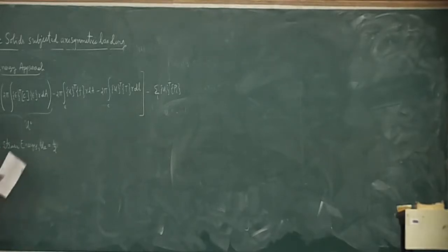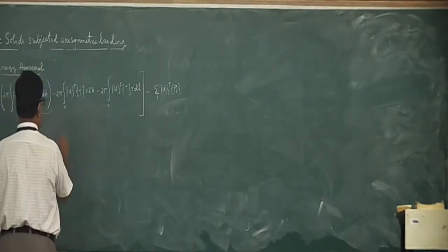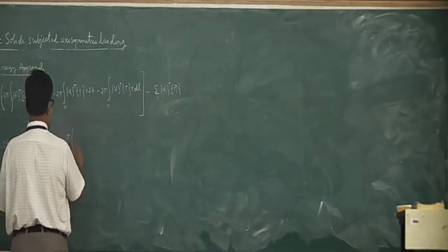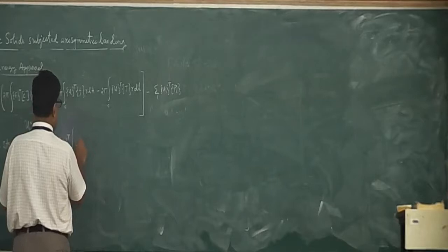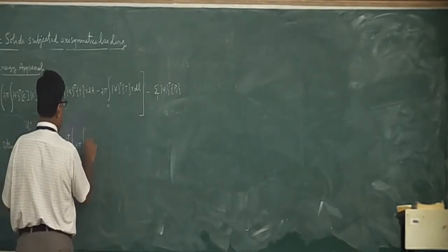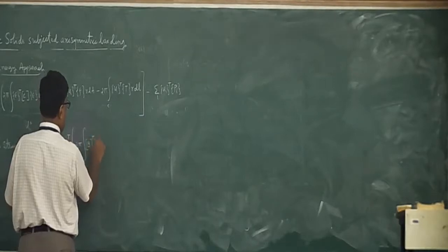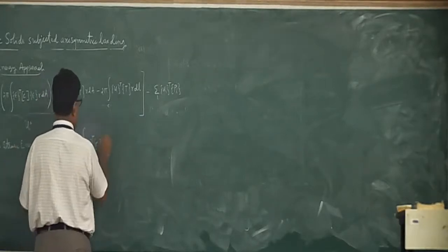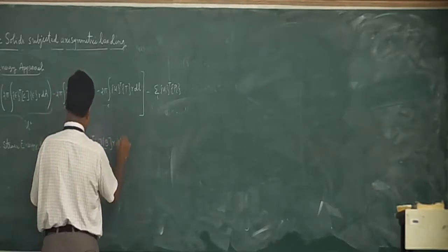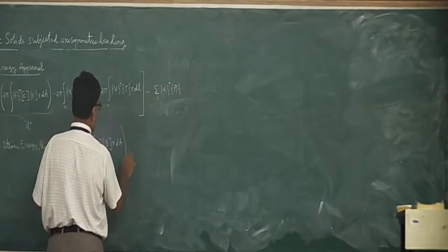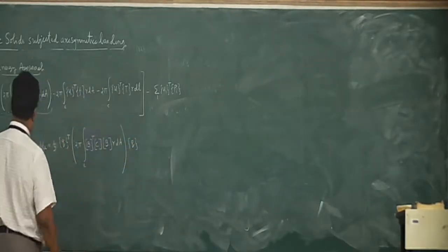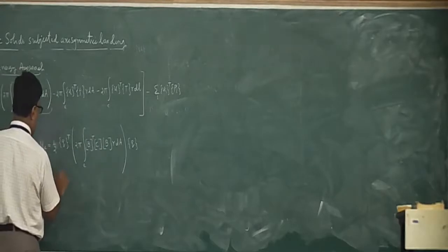So if I substitute that directly into this, what I will get is Q transpose into bracket, 2 pi will come inside, over the element, B transpose C into B into R dA, whole bracket into Q. So this is very much similar to what you used to write.